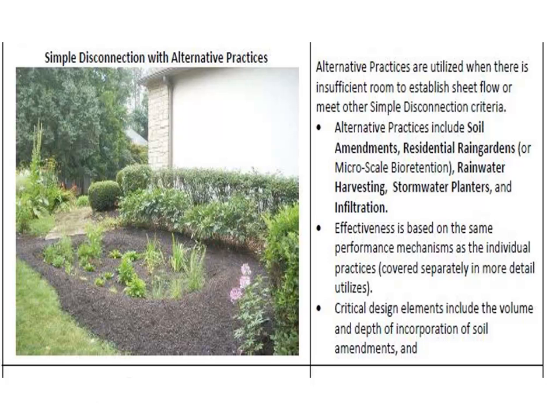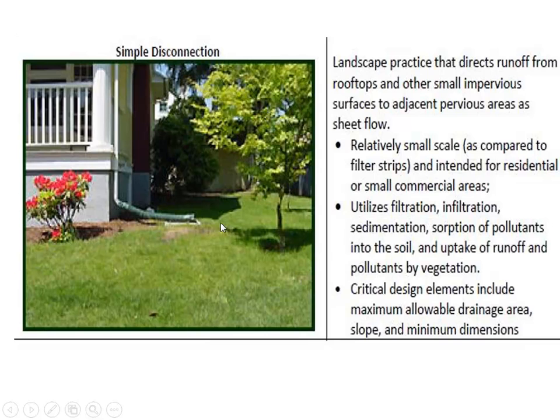Now, you can add a small rainwater garden at the end of a roof drain, with special plants and a berm built up to ensure that the water doesn't flow over the lawn. Some people might have concerns that in a heavy storm the rainwater could erode a certain part of the lawn or cause puddling.